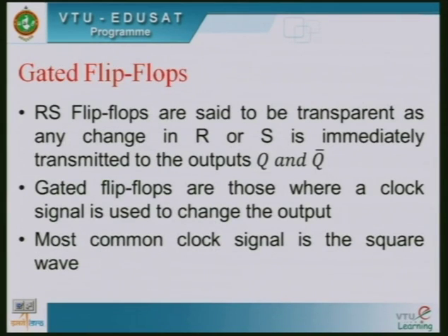Now, let us see what are gated flip-flops. RS flip-flops are said to be transparent or gated if any change in R or S is immediately transmitted to the outputs Q and Q bar. So, gated flip-flops are those where a clock signal is used to change the output. So, a clock or enable signal is needed here. The most common clock signal is a square wave.